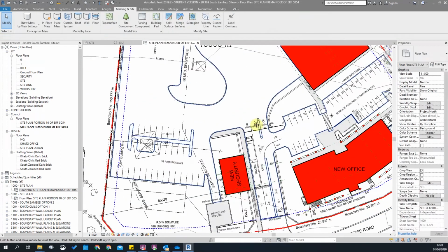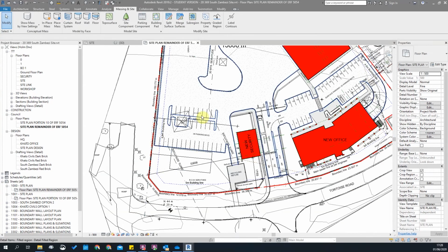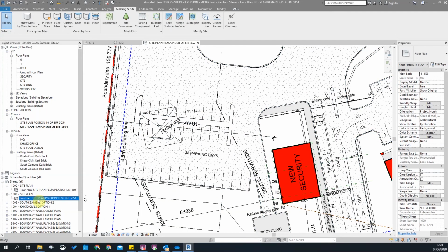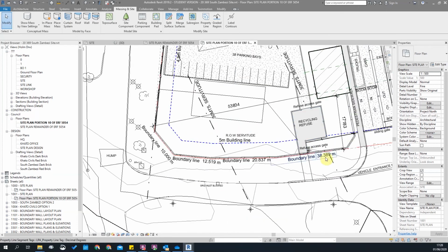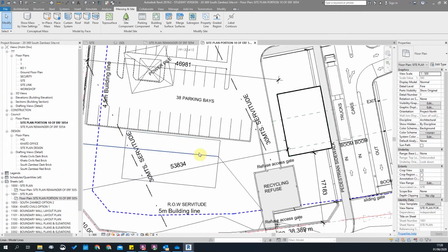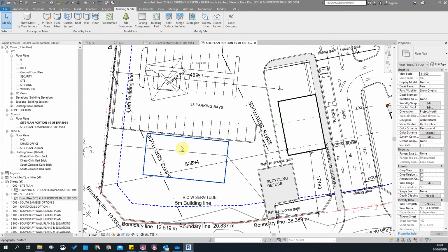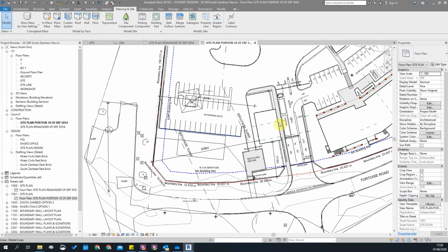Okay, but in essence, with this building pad, I'm going to look at one of these contours, for example. Let's go to this one. You need to determine on which boundary or contour line you want to start building your building from. That's critical to understand how this relates to your topography information.